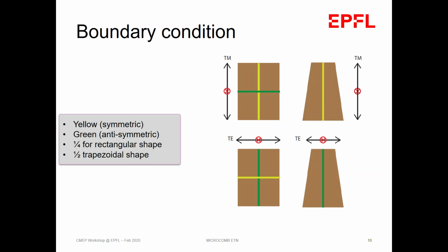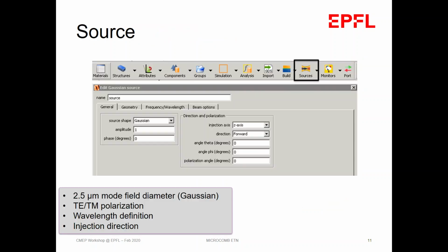So we are losing some light there as well. And what happens if you make the taper not linear, or some other shape? I think, no, not adiabatic. Like if you make a 15 micron taper, or then you have a very abrupt transition, and then you will lose quite a bit of light there for sure. And is it back reflected or is it radiated? I think radiated, yeah. You can check with the paper that we wrote, which shows a propagation profile, the guiding light and the radiation.